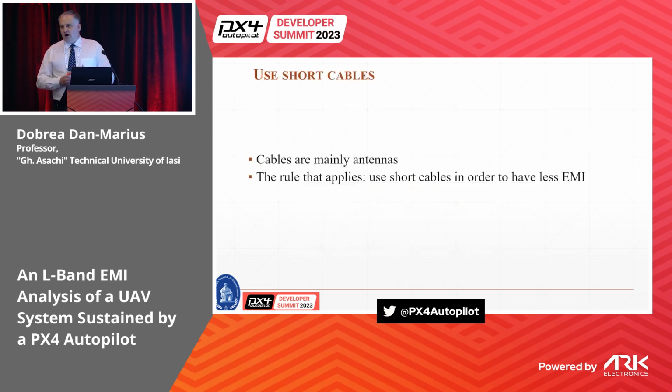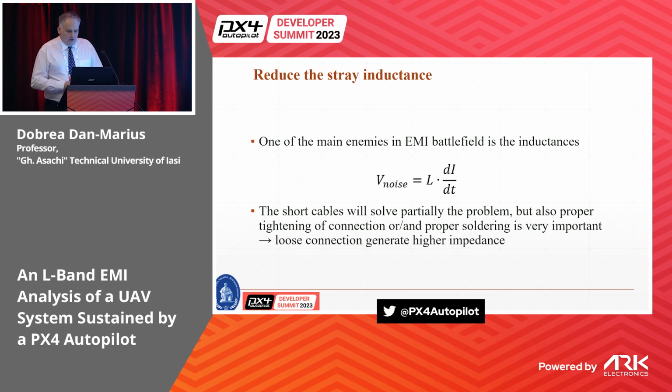Another solution is to use short cables, mainly because a cable is an antenna that is able to generate and receive different types of electromagnetic disturbances. Another enemy in the electromagnetic interference battlefield is inductance.